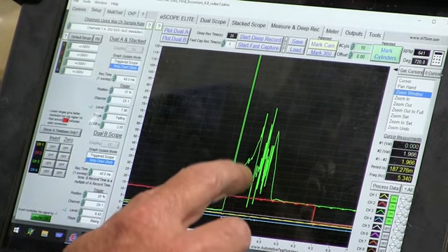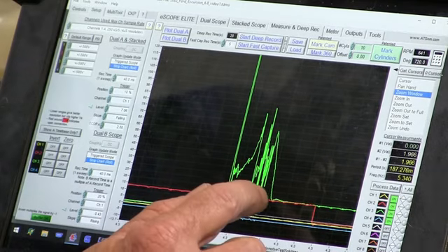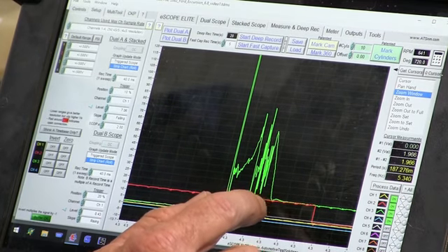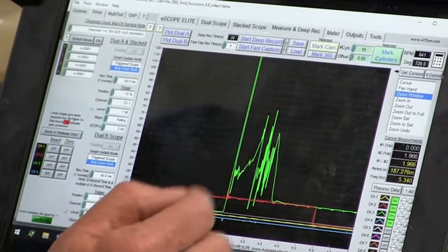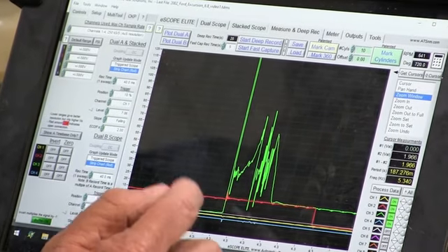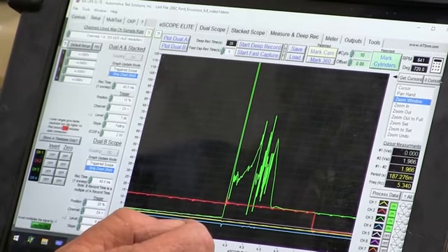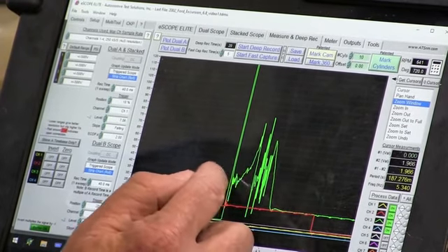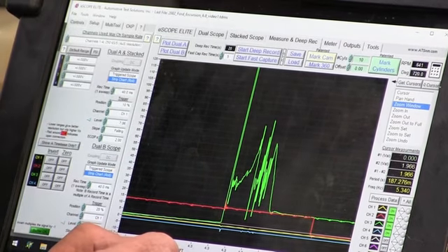Okay, look at how heavy the turbulence is right there. Really, really heavily turbulent with no tail. Now that I don't think is turbulence. I think that's carbon tracing in the coil or the plug, or there's some kind of a trace right here. I don't think that that has to do with a bad valve, but I want to do one more test.